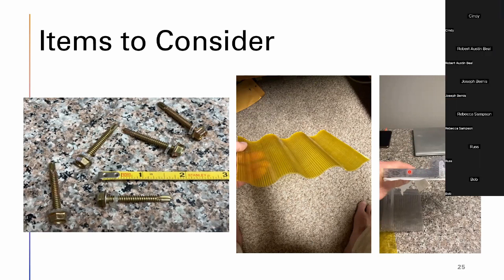The reason the Netherlands uses a single pane of glass is because they have a very moderate temperature there. They're also low on elevation with a lot of relative humidity, so they need the higher transmissibility. And they can get away without 2 layers because they don't lose so much to the radiative effect.